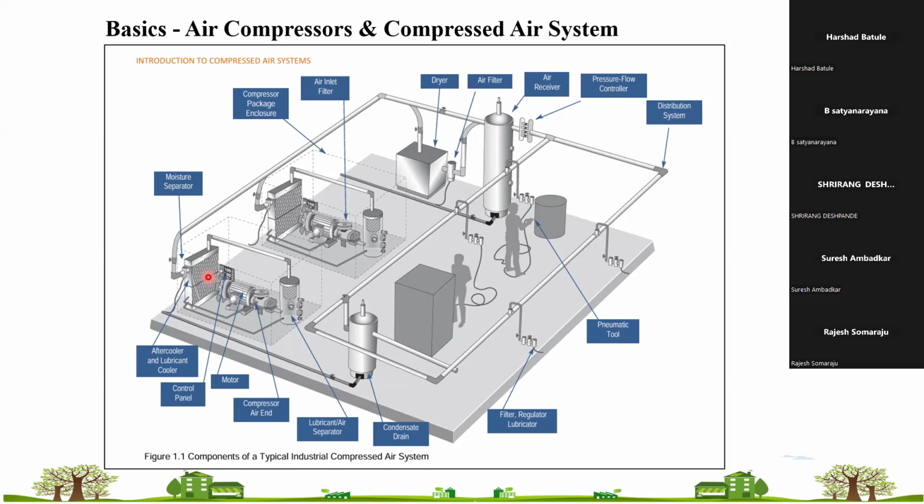So that has to be separated, because you can't allow moisture or water to be in your compressed air system, because it will damage your distribution network. It will cause rust in the distribution network, or cause harm to the equipment you are using as an application of compressed air. So we cannot allow water to flow in the system, or in the instrument here. There has to be no water at all in the compressed air network.